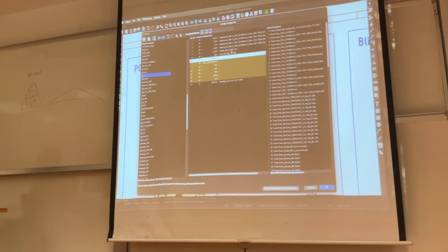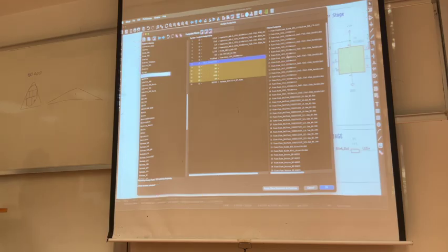After that, polyfuse, I come to fuses. 1206, hand solder. I click to hand solder. I normally click on hand solder, but in my version it doesn't show a footprint. So we're going to use schematic. It is the same. When you have a hand solder footprint, it just makes the pads larger so that you can use your soldering iron on it. So it makes it easier.